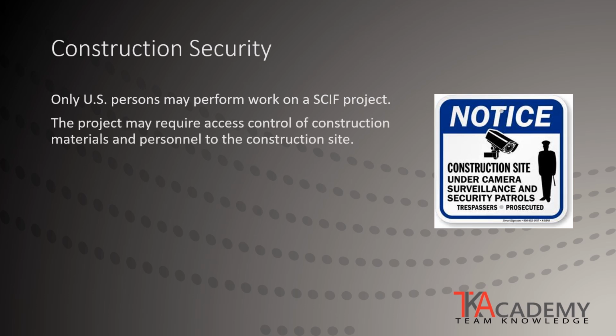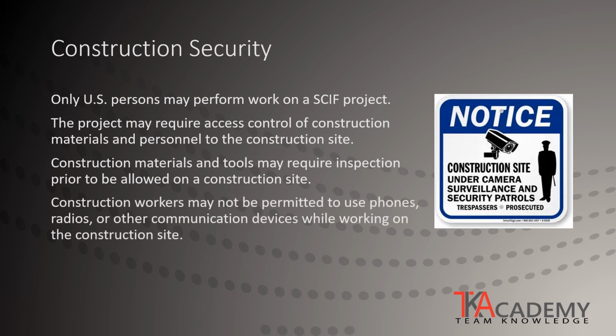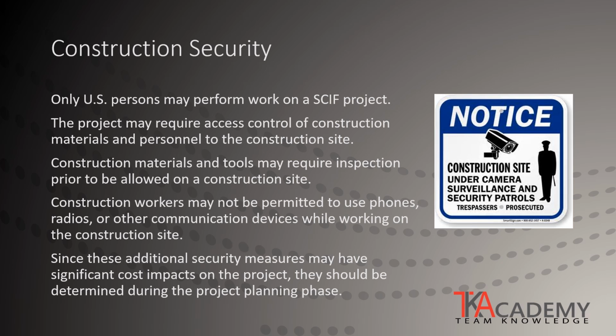The project may require access control of construction materials and personnel to the construction site. Construction materials and tools may require inspection prior to being allowed on a construction site. Construction workers may not be permitted to bring phones, radios, or other communication devices onto the construction site. Additional security measures will have a significant cost impact on the project, so they should be determined during the project planning phase.